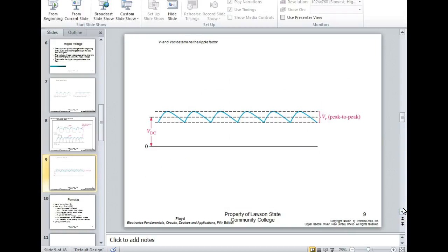And this is what they're showing you. That's why we use that formula, because my DC average is not up here. My DC average is not right there. My DC average is where? Down the center, because it's a repetitive AC waveform. And if you've got a repetitive AC waveform, your average is going to be right in the center, no matter whether it's a sine wave or any AC waveform, right? You understand that? But here we're riding it on top of DC.